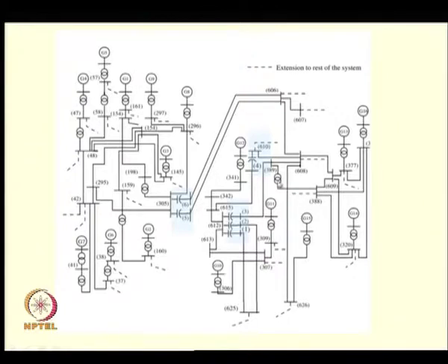So, you can have many subsynchronous network modes and many torsional modes, and you have to do a linearized analysis to check the actual effect of all these network modes on individual turbine generator shafts.